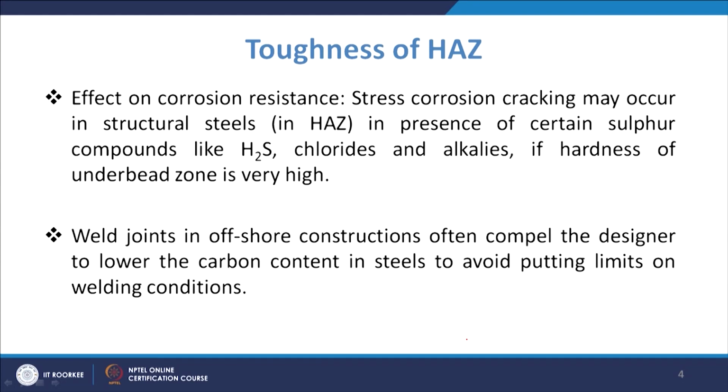In those cases we try to limit the hardness to maybe 150 to even 200 or 250 maximum. So, that stress corrosion cracking is another point which is very much to be kept in mind when we talk about the properties of the HAZ.